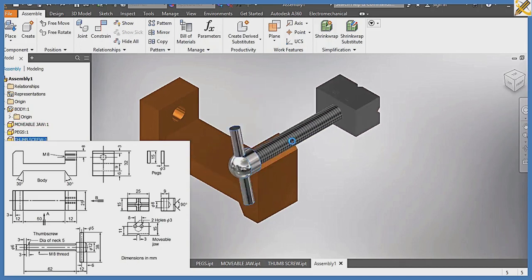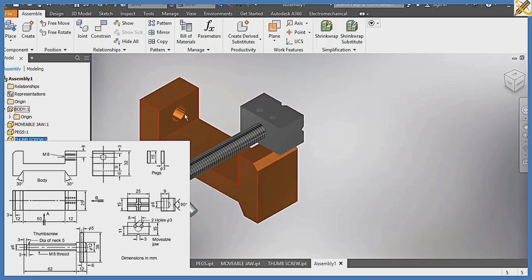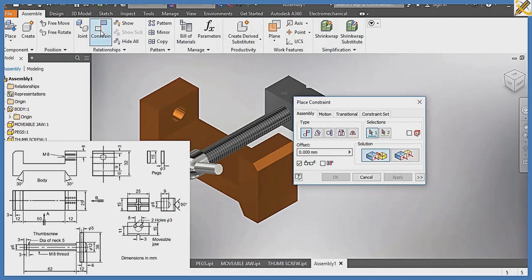So how do we place the complete of this inside this area now? The very first thing is I need to align the whole of this to this particular plane. They need to be in alignment. So how do I do that? I'm going to click my constraint, and then click on angle. You can see this object right here is perpendicular to this, which is angle 90. So if I want to make it on the same plane as this, it is going to be at an angle of 180. So my angle is what?